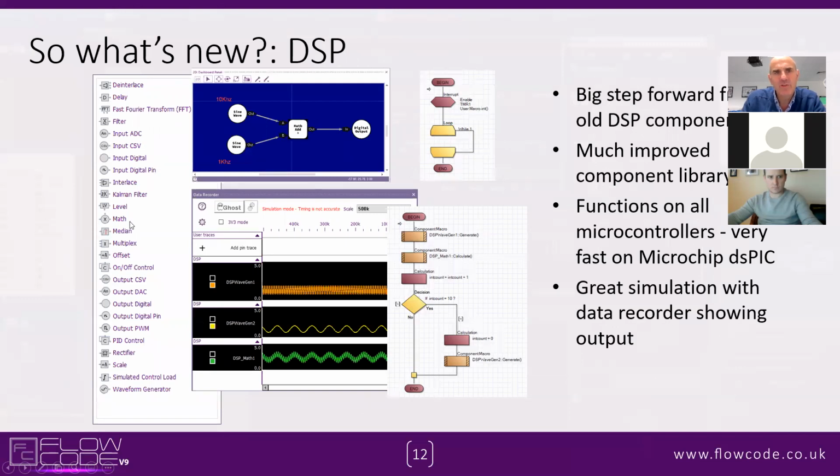And all of this is interrupt driven. So basically you declare an interrupt inside the workspace, inside the flowchart, and the interrupt calls a macro, and in that macro you basically call the appropriate routine for each of these icons that you want. So you say to the wave generator, generate me the next value, generate the next value for this 10 kilohertz one.